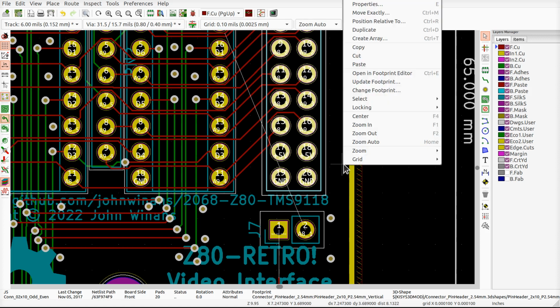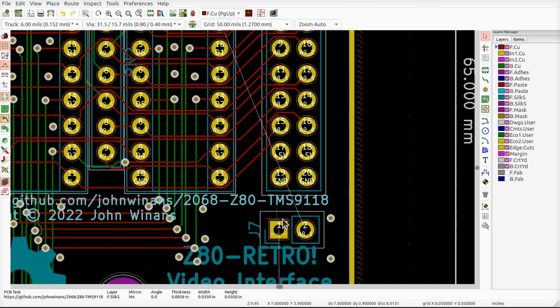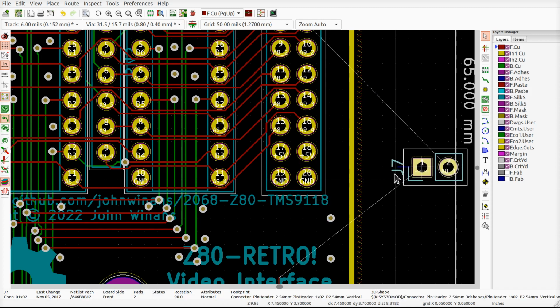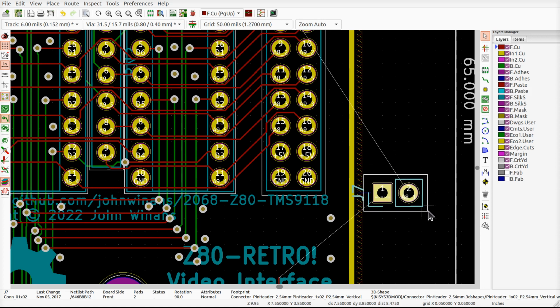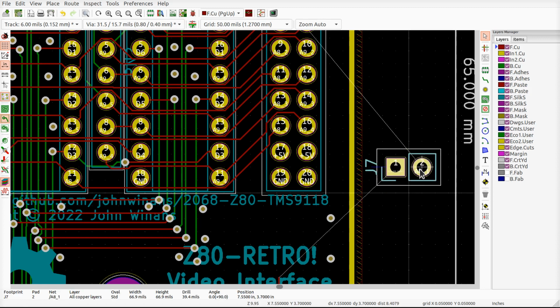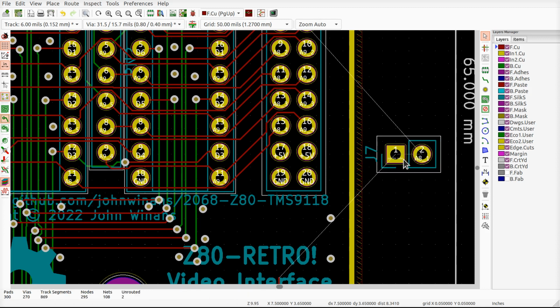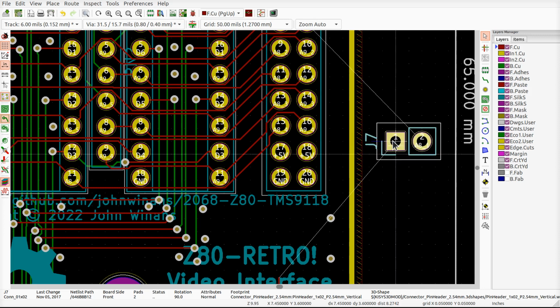I don't know, is that right? Let's see here. If I go to, you know, like 50 mils and grab the part here, if I move it around, okay, so if I move it, and on pin 1 when you move it, sometimes you go grab something that you move it like that. Let me see if I click over here. This is like a KiCad thing. See how I've selected this pad over here and I hit M? Notice when I'm moving it now, the cursor's centered on the pad that I selected. But if I select the whole part and I hit M, it's now centered on pin 1.